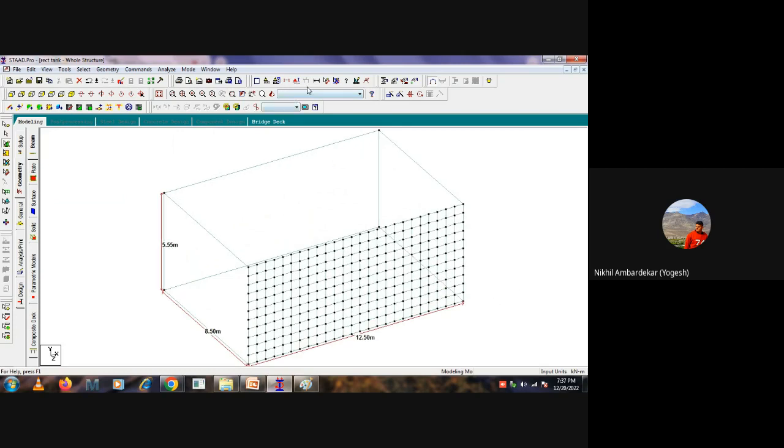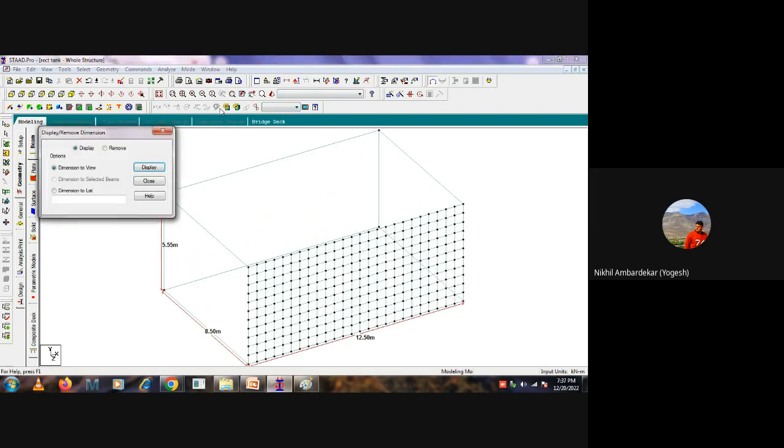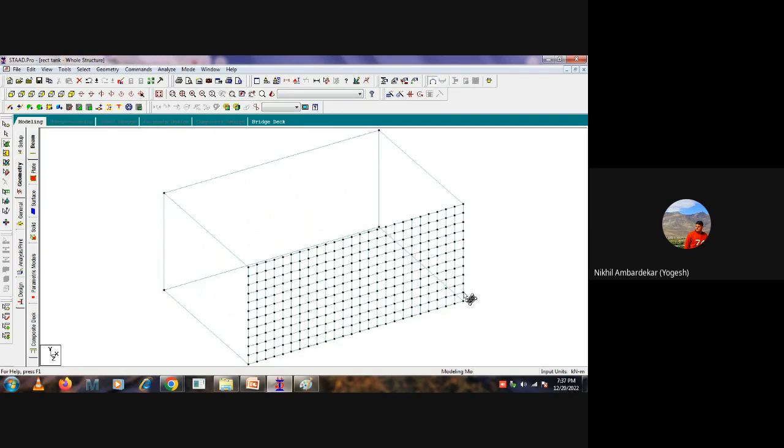So if you again measure this aspect ratio, 0.5, 0.5. So it is almost 1. Okay, so that is most desirable, but it's not hard and fast that it's absolutely 1. It is okay if it is 0.8, but between 1 and 2 will be most desirable. Okay, so same thing that we need to apply for this wall also.